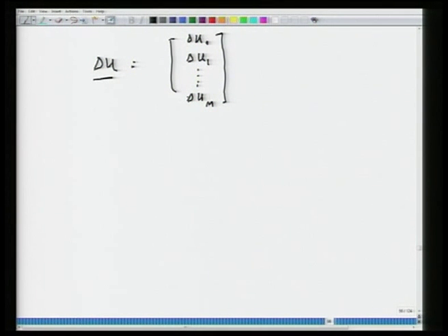At the current time instant, this one gets implemented. So, this control move gets implemented, and then I wait for the next sampling instant. At the next sampling instant, I get my new measurement, and then I repeat this whole process all over again.